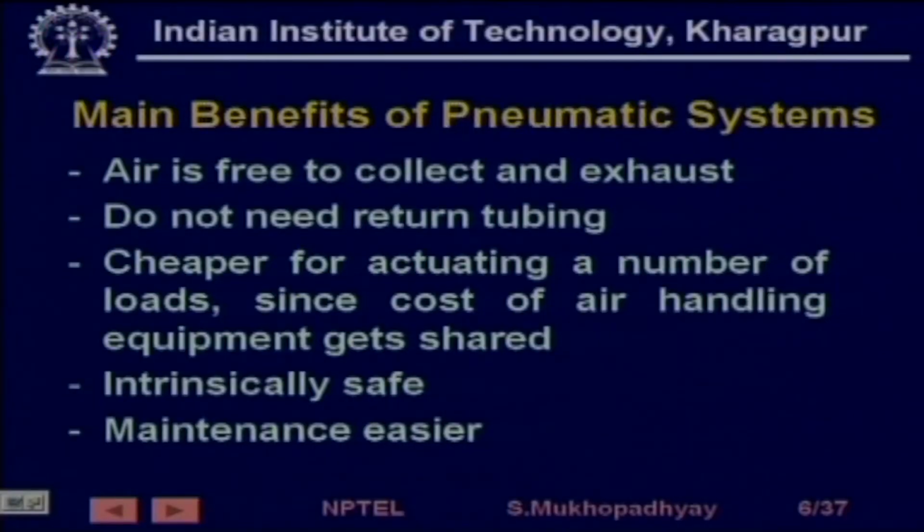Now, there is another important advantage of pneumatic systems. While electric systems are prone to fire because of electric sparks and hydraulic oil is inflammable, being a petroleum derivative, pneumatic systems are intrinsically safe and therefore often preferred in places like explosive environments. Let's say a natural gas plant would have a lot of application for pneumatic control systems to be free from the hazard of explosion.